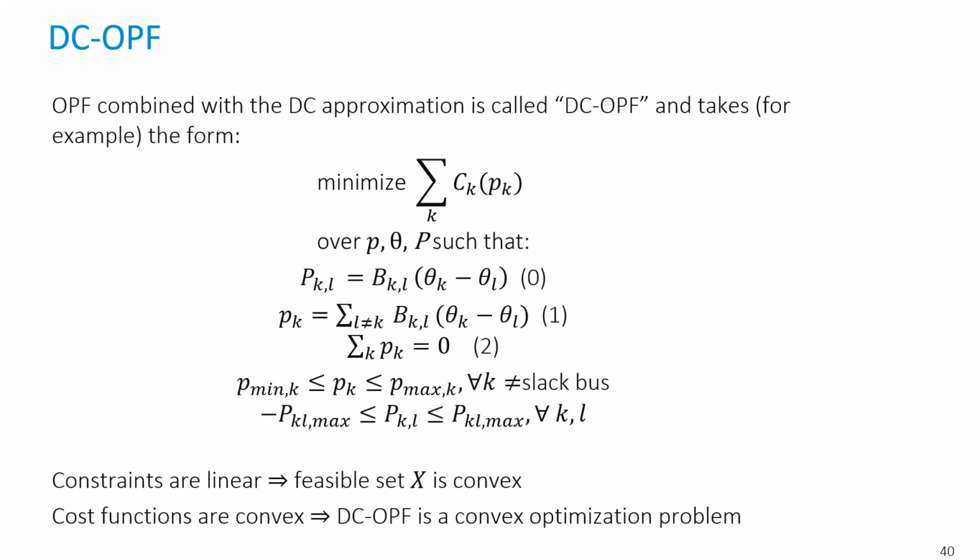We will see other techniques for that, where we'll use other forms of linearization that capture all the properties of the grid. But the DC-OPF gives a first global solution to the problem. That's something very common when you have a non-convex problem. If you have to solve a complicated non-convex optimization problem, you will typically always do it in 2 steps.